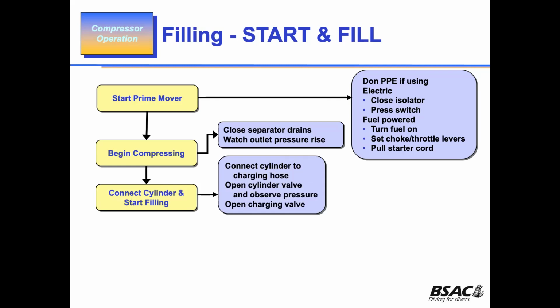You begin compressing. Close the compressor drains, watch the outlet pressure rise. That's what happens. Connect the cylinder to the charging hose, open the cylinder valve, and you observe the pressure. Open the charging valve, right? So once you start there, you'll see the pressure start to go up.